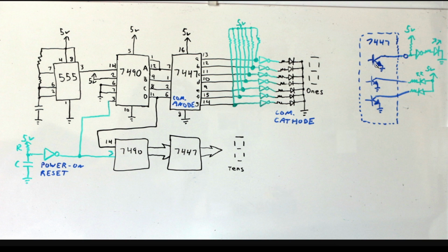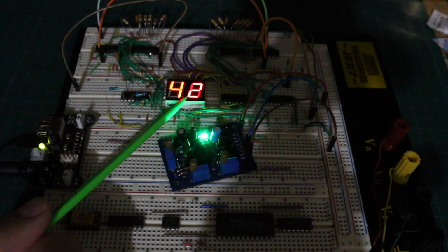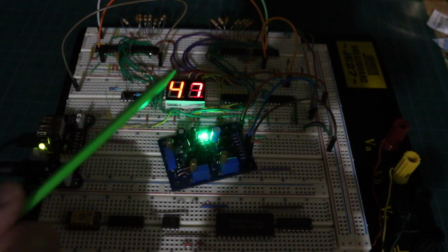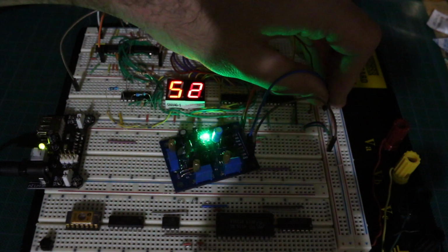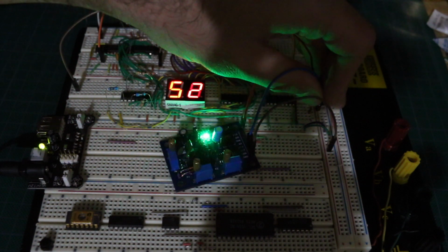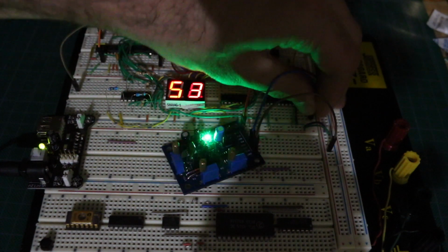When the output is supposed to be on and this transistor brings a low to the input of the inverter, we get a high output and the LED segment turns on as required. So I'm converting this common anode driver into a common cathode driver. In order to use this to select a winner for the draw, if I pull the clock, the display will just pause. And when I add the clock, it will resume.